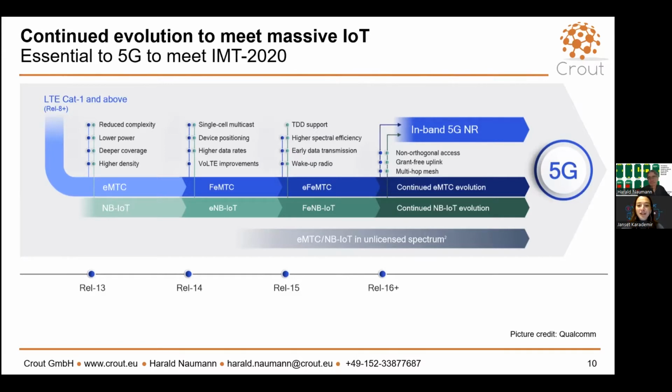And lastly, this is about the speed and stationary devices. Which technology is better for stationary application? Is it NB-IoT or LTE-M? Both is fine. The main difference between narrowband IoT and LTE-M is in the economics. If you get a narrowband IoT chipset, and that means a narrowband IoT module, you get an estimated half of the price of LTE-M combined devices. So if there is a high price pressure, then you end up with narrowband IoT.